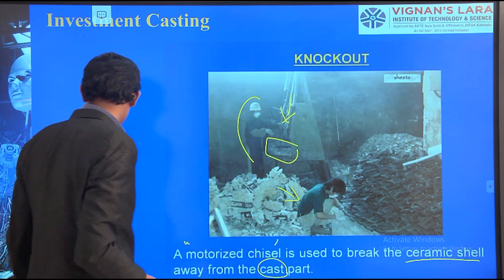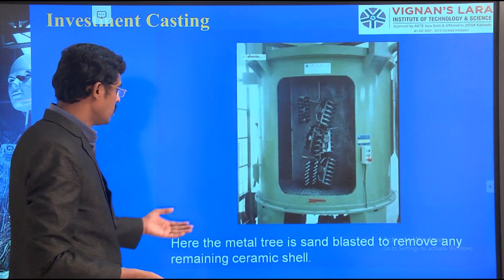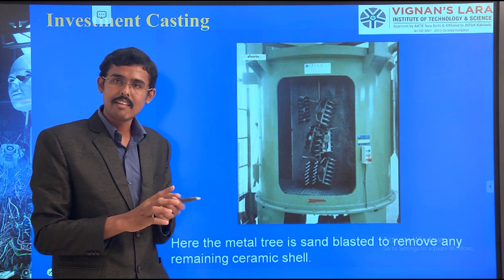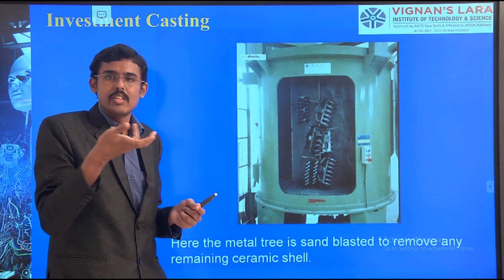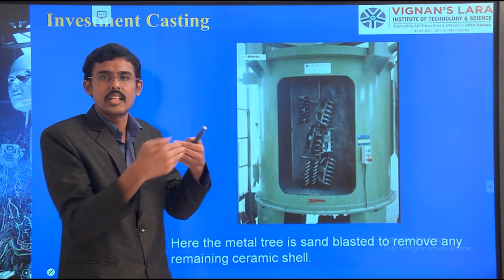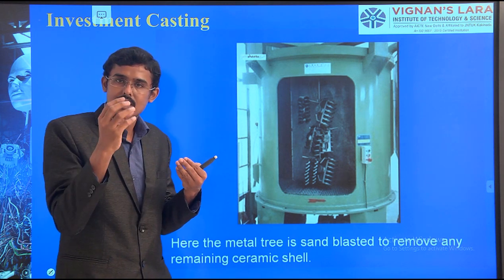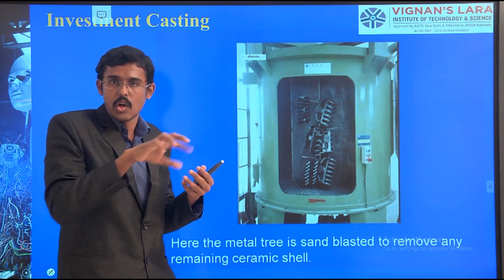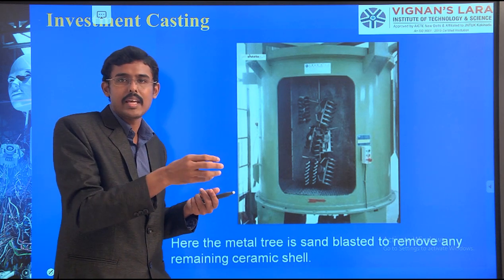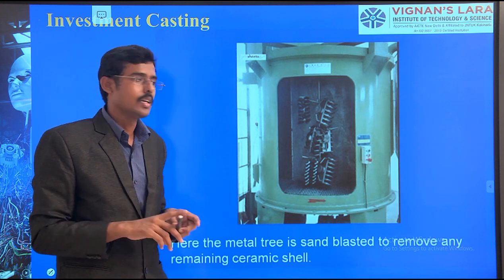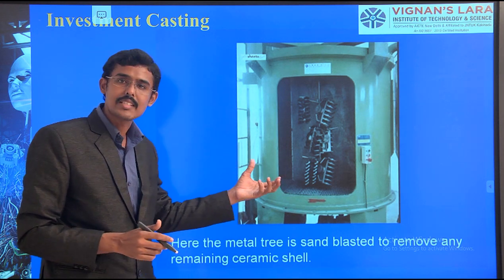You see, right? So after doing this ceramic shell breaking process, there will be parts having complex designs or corners inside here and there. What happens? This ceramic is already kept inside, meaning already fixed inside. It should also be removed. By a simple breaking process, manually it won't break. Therefore, what I am doing is using a sand blasting process.